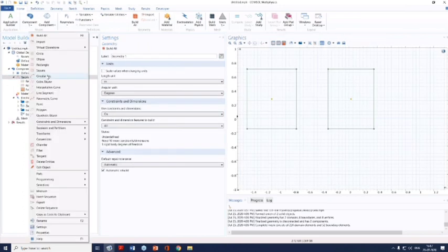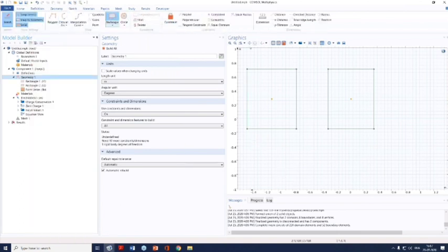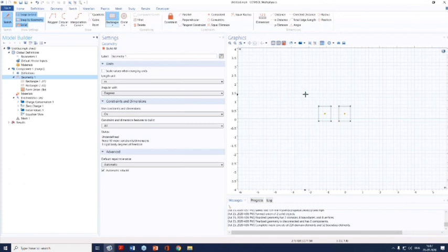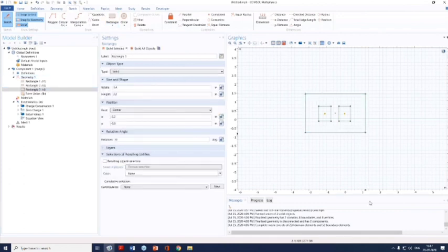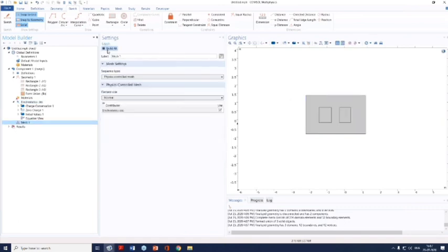In order to have communication established between these two, what one can do is go to the sketch node again and enclose both of these in one box. If I go to electrostatics now, and then to mesh, you'll see that the entire domain is getting meshed. So there is a connection, there is a space. It could be the entire domain, or you can just draw a small path over here. This is based upon what physics you are solving for.